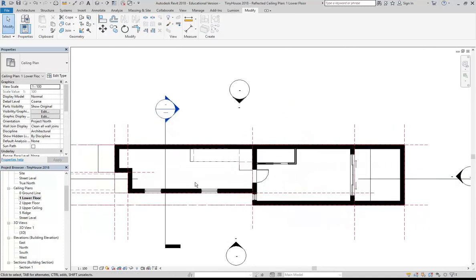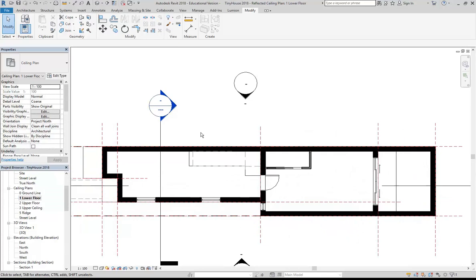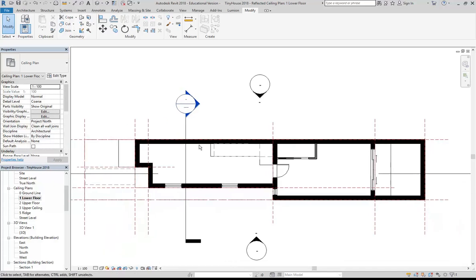So that's really the most important thing, and really the only reason I'm showing you ceilings. If you didn't need to put lighting in, then it might be easier just to thicken your floor. If you're going to line that to create your ceilings, you could just extend the floor structure down rather than adding in a ceiling. But if you're going to place lights, then you need to have a ceiling object, or Revit won't recognise them.